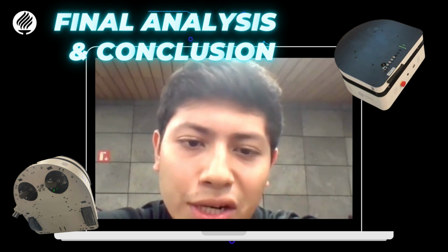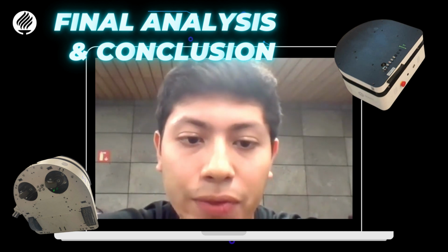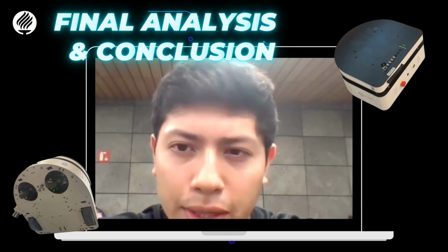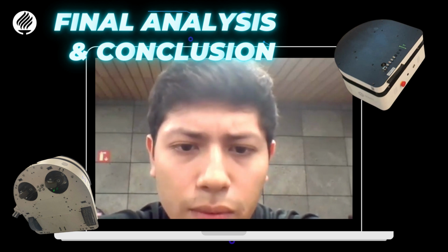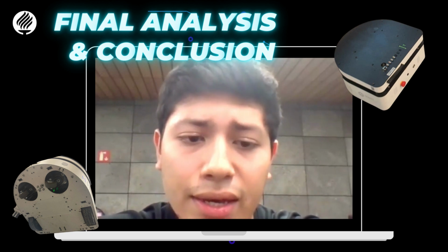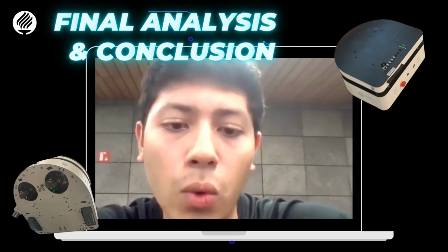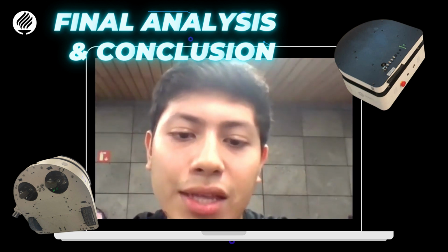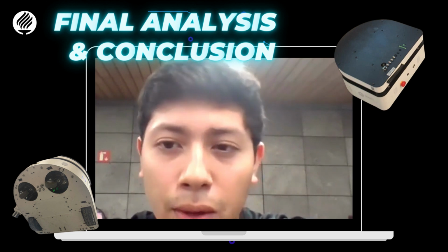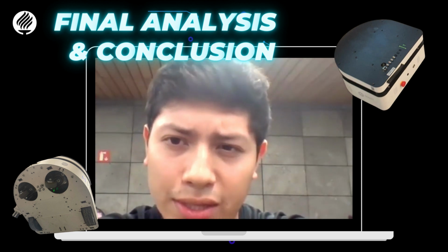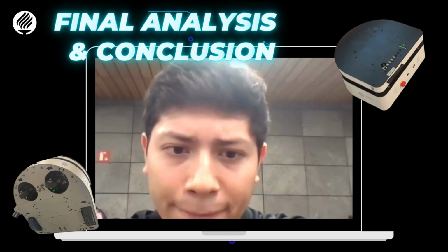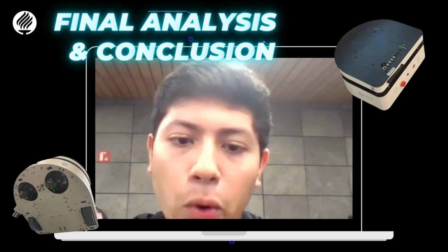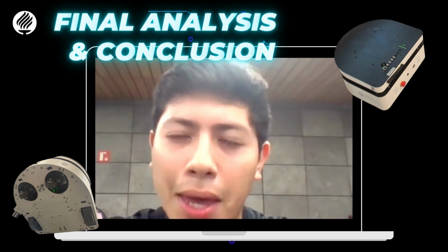And these results are supported by our experiments, where in the second translation experiment, the one of the 4 points, we observed significant disturbances in the movement when a prior calibration was not performed. Due to the low speeds and the absence of consideration of the robot mass, we had a bad result in that simulation. In contrast, in the first simulation, we placed greater emphasis on the calibration to achieve more precise movements because we wanted to have a better square.